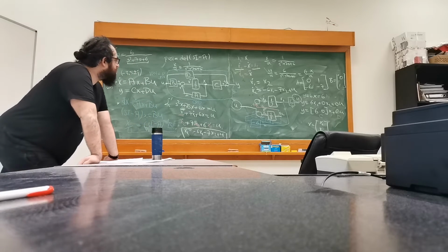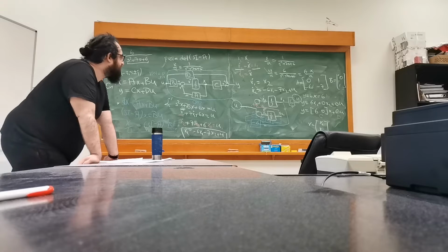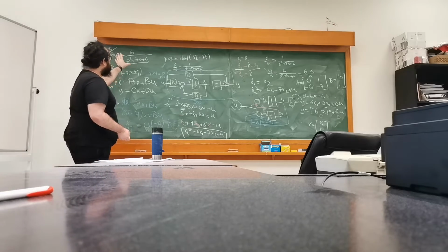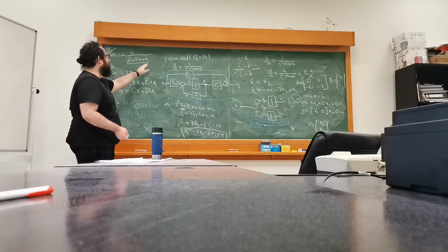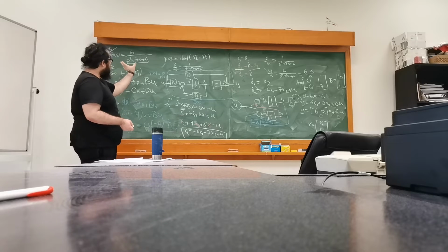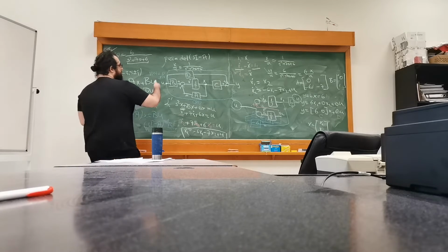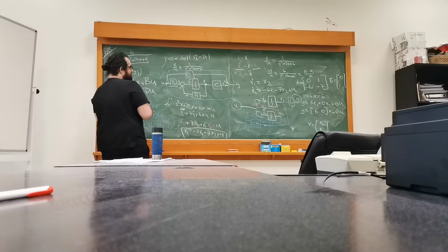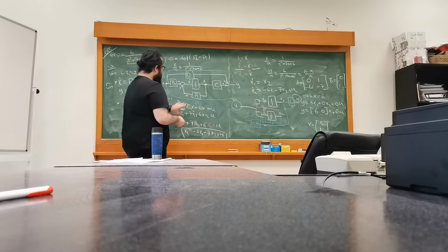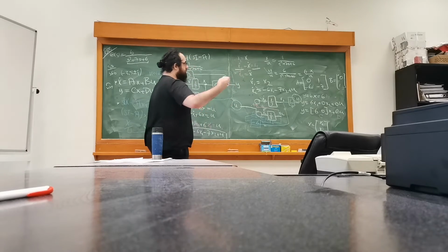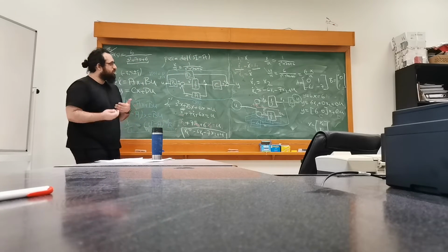So, yeah, I've written a lot of stuff, but let me recap. We have this relation here, 6 divided by s squared plus 7s plus 6. But we only care about the characteristic polynomial, or the denominator. That will be the state to input relation. And we cross multiply them, obtain the corresponding differential equation, the higher order one, and then introduce new variables at each derivative in order to reduce the overall order.